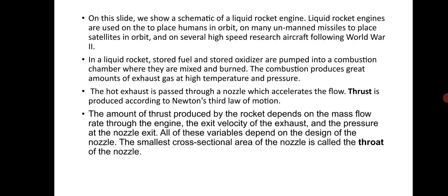In a liquid rocket, stored fuel and stored oxidizer are pumped into a combustion chamber where they are mixed and burnt. The combustion produces a great amount of exhaust gas at high temperature and pressure. The hot exhaust is passed through a nozzle which accelerates the flow. Thrust is produced according to Newton's third law of motion.